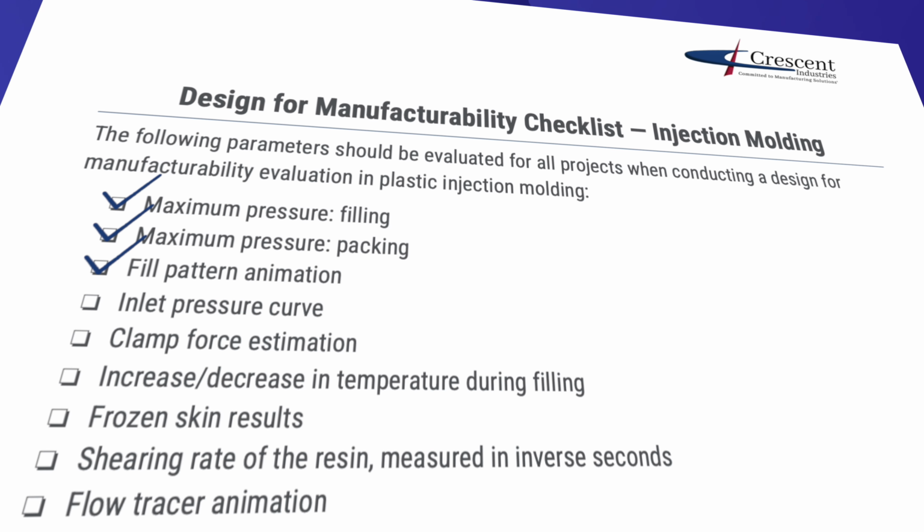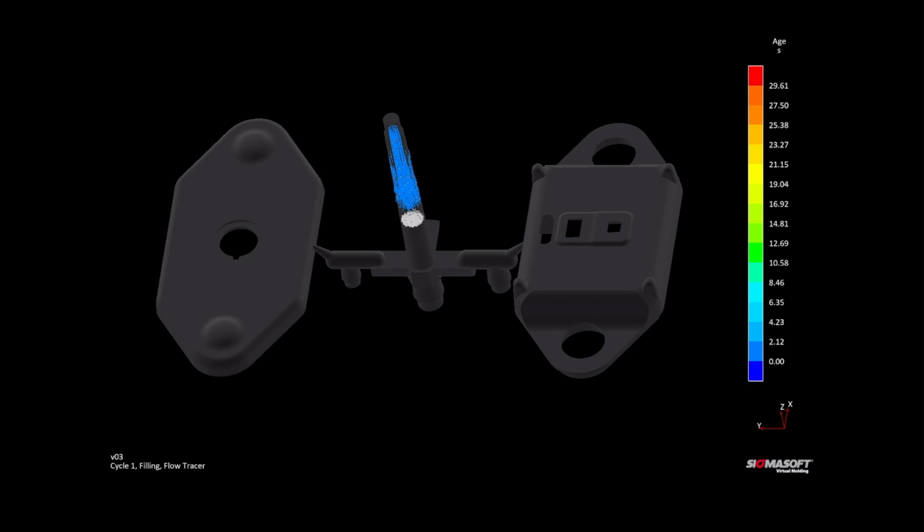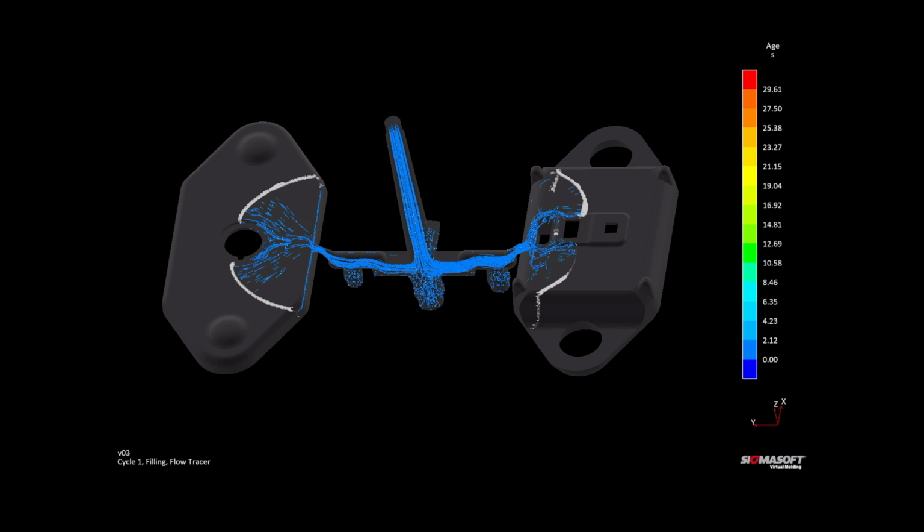Thankfully, we use advanced mold fill simulation software that shows how the molten plastic will flow through the cavity, and we're looking for balanced, even fill here. If the flow is uneven, too slow, or racing through certain areas, you're more likely to see certain defects.